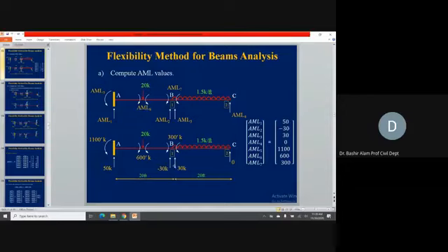Here at B, if we want to find the reaction, it will be 30 kip. This 30 kip comes from 1.5 times 20, which is 30, in the upward direction. Just to the left of this section at B, it will be 30 kip in the downward direction. Under this one, you can find it, but we don't need to because we don't have any vertical reaction here. We have a moment here only. What will be the reaction here? It will be 1.5 times 30 plus 20. So this is kind of finding the shear force and bending moment values at various sections.